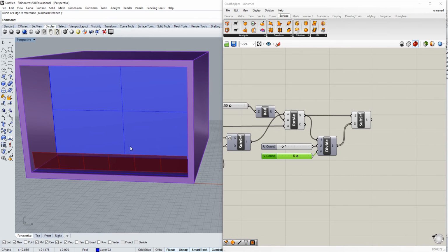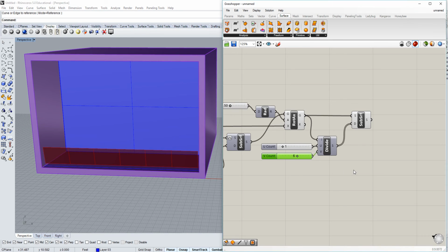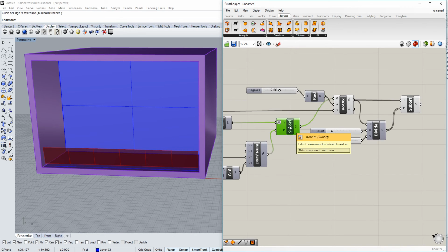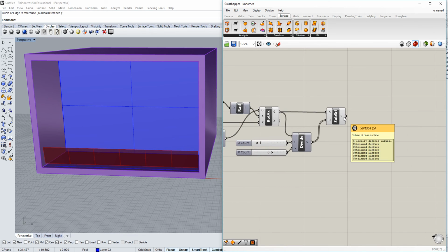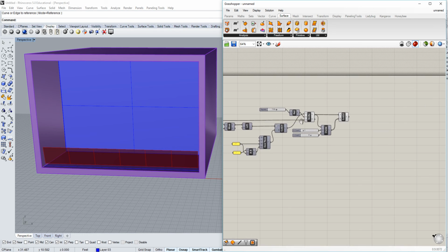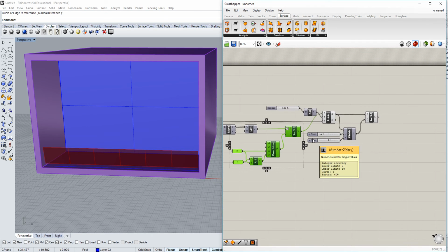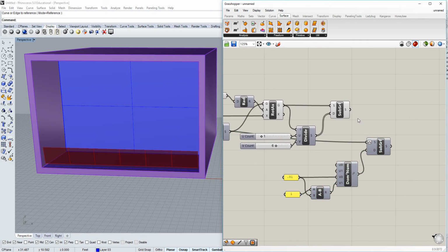So at this point, you should have something like this. And now we have just 2 steps left. We're going to reduce the size of the panel, and then we're going to put pipes on the rails, basically. So again, using a similar construct to reparametrize the individual surfaces, we can reparametrize them right here, because that's a set of untrimmed surfaces. So I'm going to take this and copy this whole construction and just plug this isotrim into this isotrim with its reparametrization.